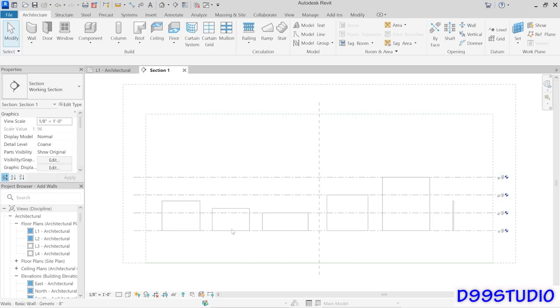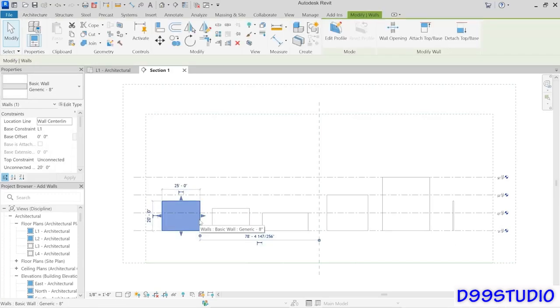And then we've got our 5 walls here and then our perpendicular one there, which we're going to look at in just a few moments. So let's start with these 2 on the left. These were both left set to unconnected. So you could now come over here and type in a different value and go ahead and put in any value you like. And notice that the height of that wall will change, and it only affects that one wall that you have selected.